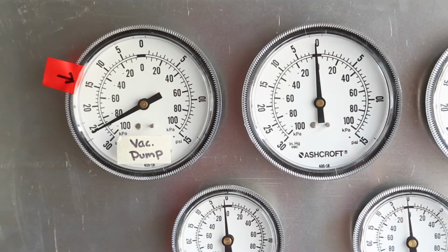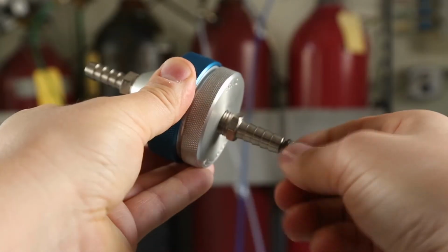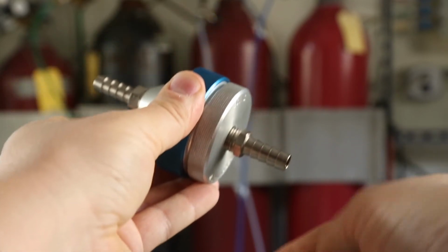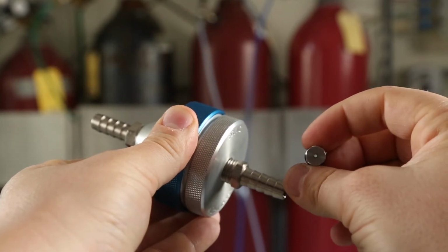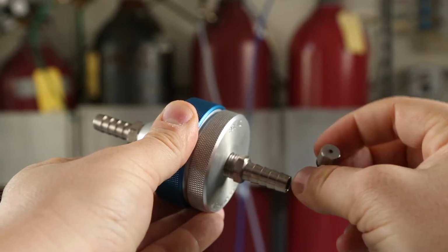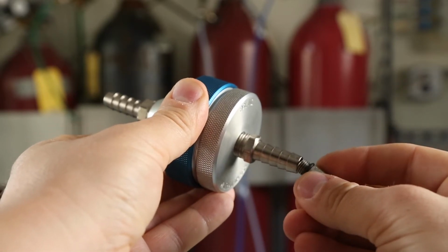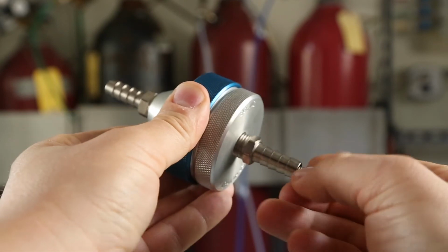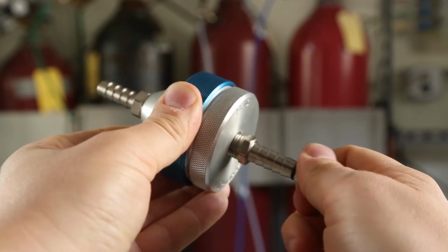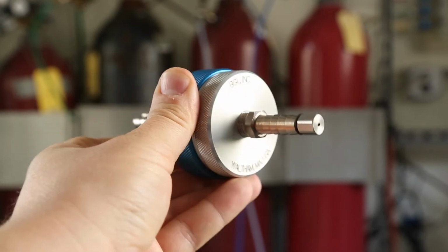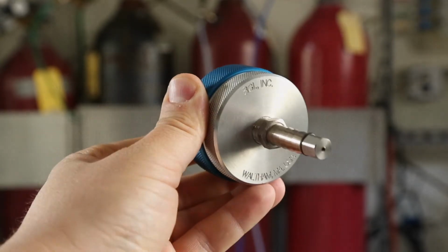Choked flow is very convenient because, no matter how much more vacuum is applied, the mass flow rate of air through the orifice will remain constant. In other words, as long as your pump can supply more than the orifice's critical vacuum pressure, you can be guaranteed a constant flow rate through the orifice. This vacuum side flow control is essential for ensuring the constant flow rate that your aerosol size separator needs.